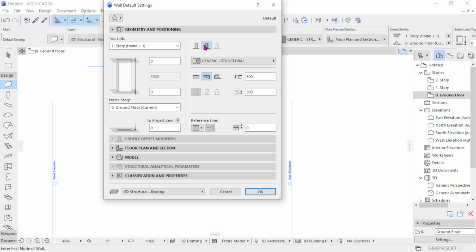So again, if I choose the composite, you expect the same. With this kind of polygonal wall, these ones are inactive, or actually they are read-only. So generally we can conclude that these types of wall complexity are only applicable to the straight geometry method of a wall. And for this particular kind of wall, you can choose the thickness. For example, what is the thickness of this wall? So this is a straight wall.